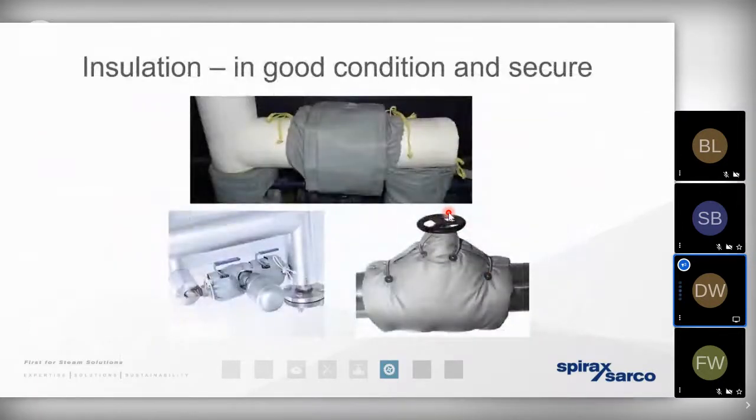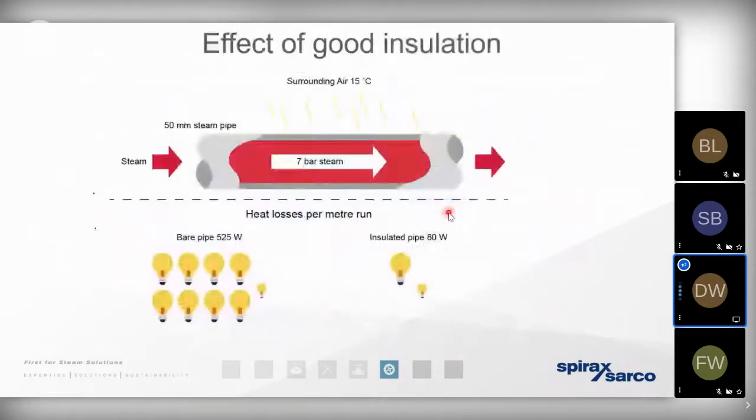We also know that insulation is critically important and it's often overlooked. And the primary reason for that insulation is actually for health and safety. It's so that we don't have anyone banging the head or putting the hand out against a hot pipe work. But we also remember that if we've got, let's say, an oversized steam pipe, if that oversized pipe is running a significant distance outdoors on a very, very cold day, we're going to get a significant amount of heat loss there.